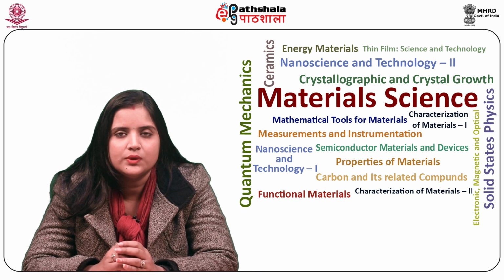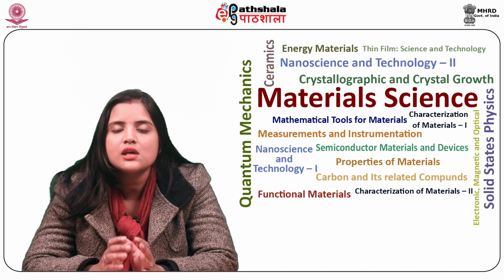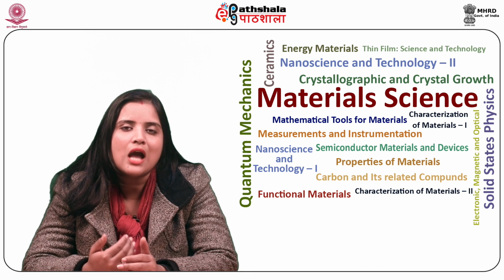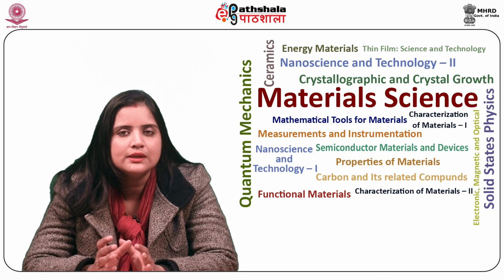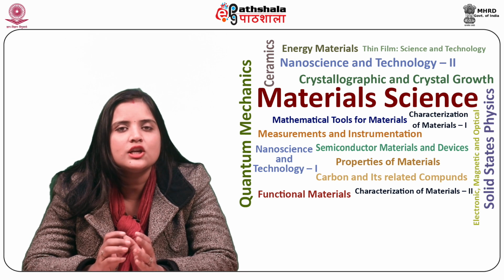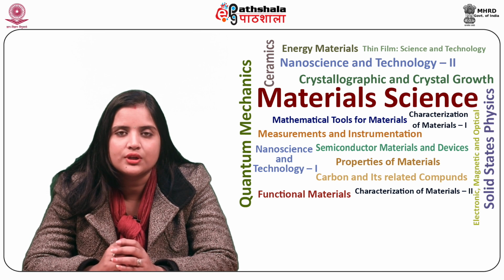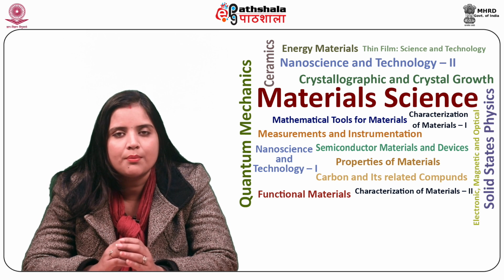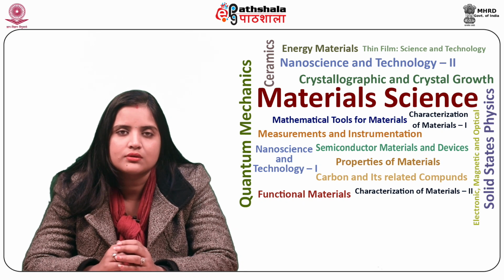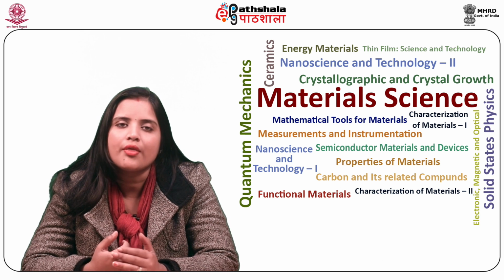Another advantage of CVD is that besides depositing a wide array of materials, it can deposit extremely high purity films. This is due to the comparative ease in removing impurities from the gaseous precursors via distillation techniques. Further advantages are fast deposition rates, along with the fact that it does not involve as low a pressure as the PVD process. So students, let us now summarize what we have learned in this module.